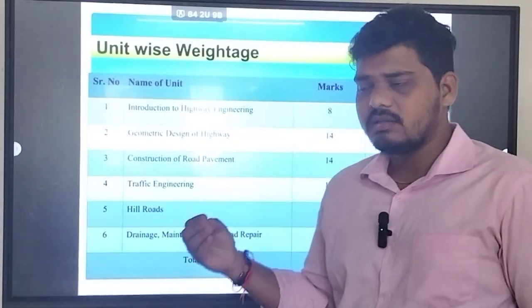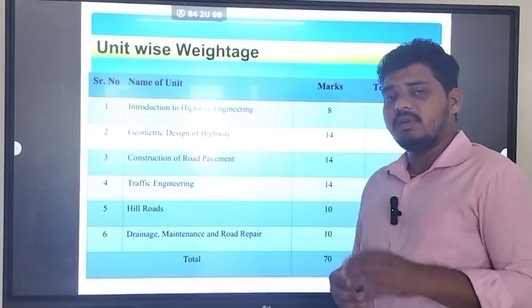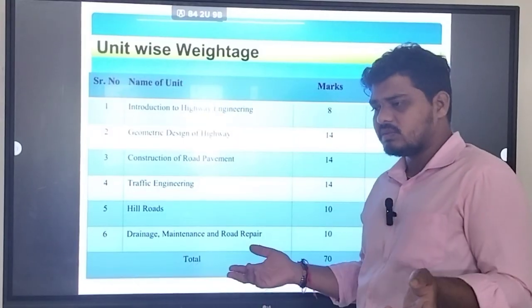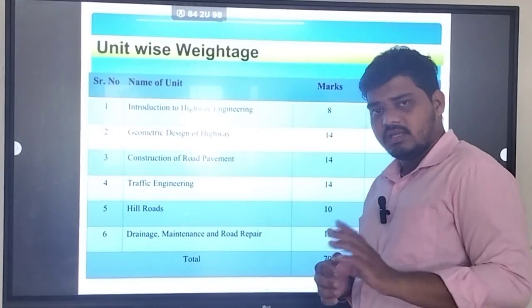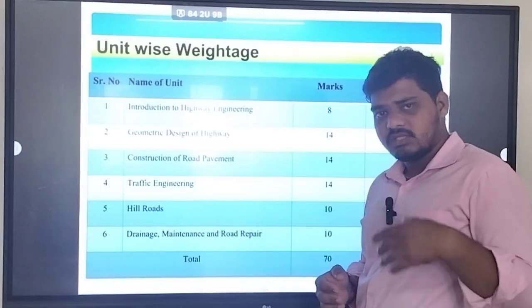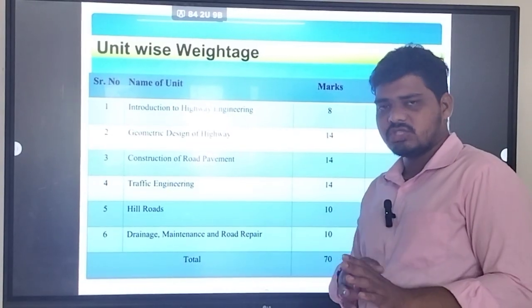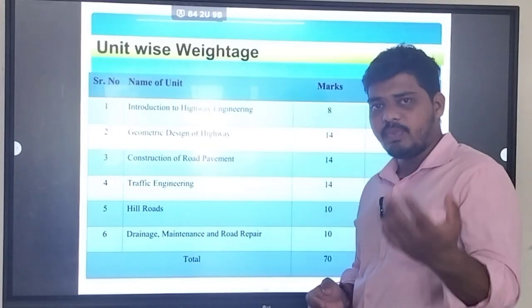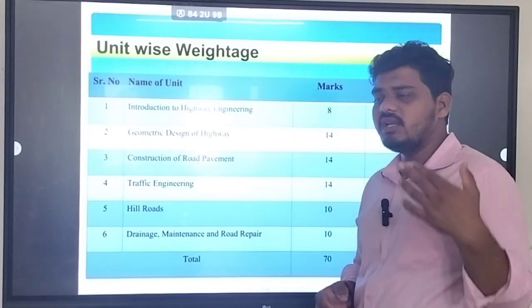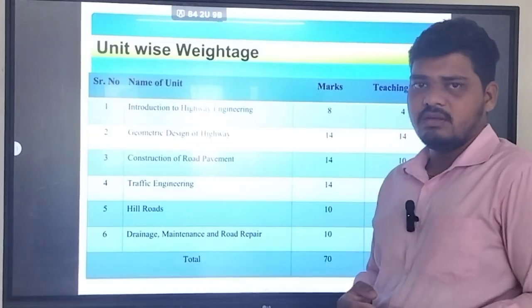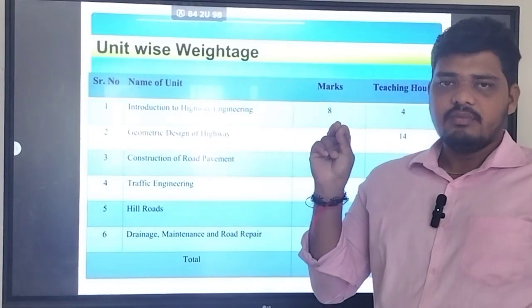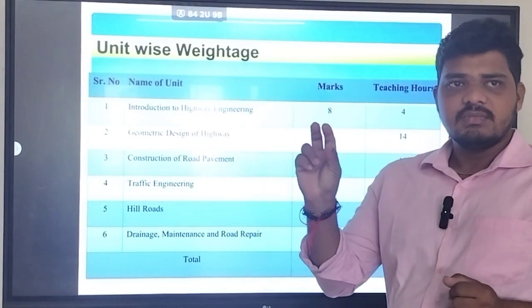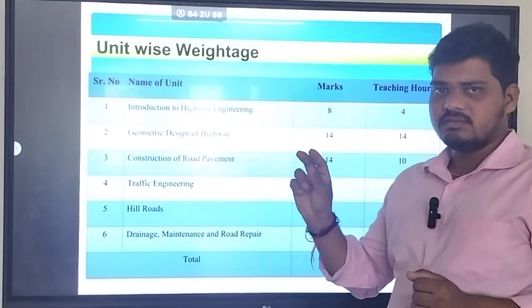That is in case of rigid pavement. In flexible pavement also, first the ground level is embankment. Then subgrade, that consists of soil only. Then subbase. Then base, then binder course, then wearing course.